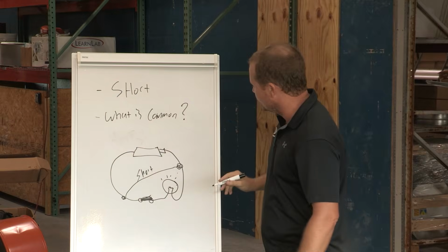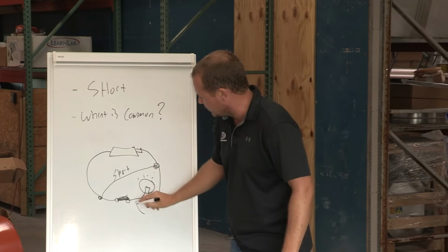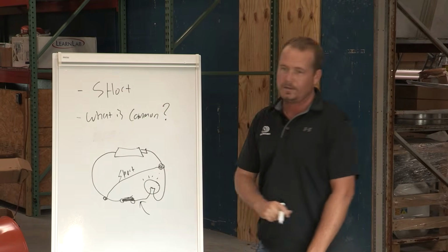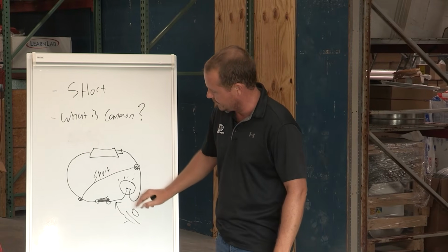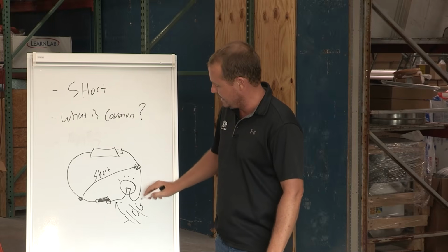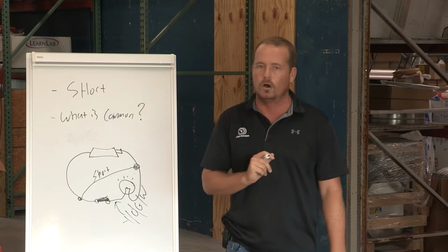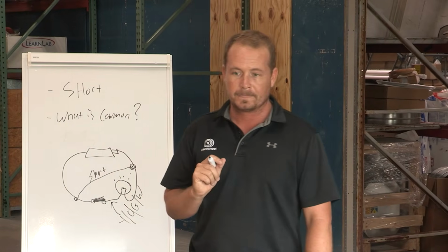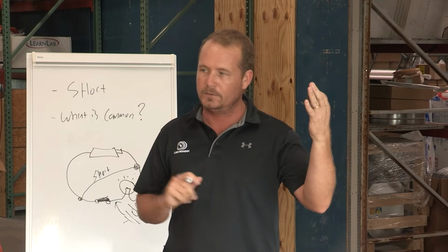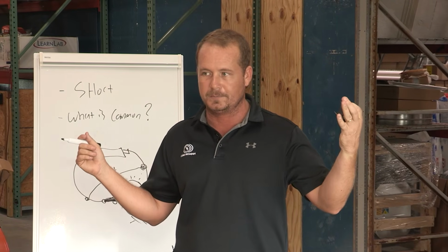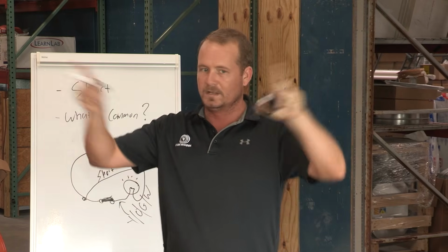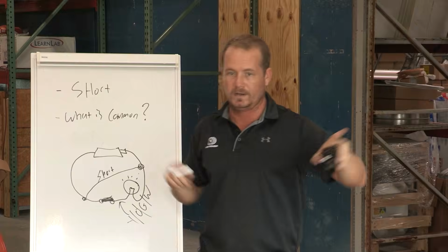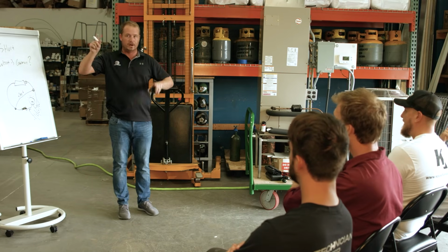So most of what we're working on in terms of our circuits are in between our switch and our load. So that would be things like Y, O, G, W. Those are all standard circuits that are in between the switch, which is what, by the way? What is the primary switch in a typical air conditioner? Thermostat is the switch, right? It's the traffic cop. It's the one saying who goes where, what turns on, what turns off, in the right order.